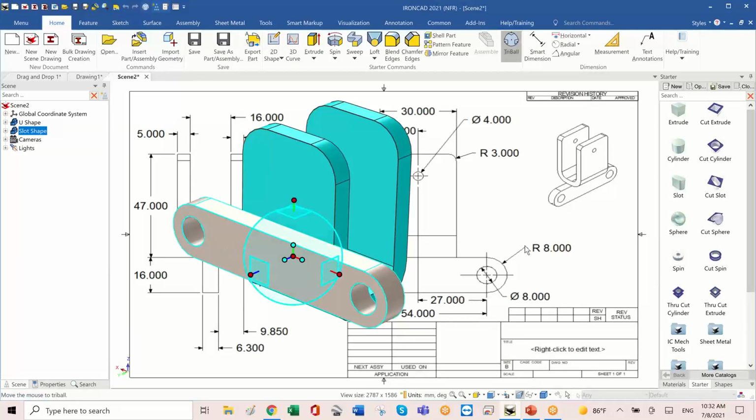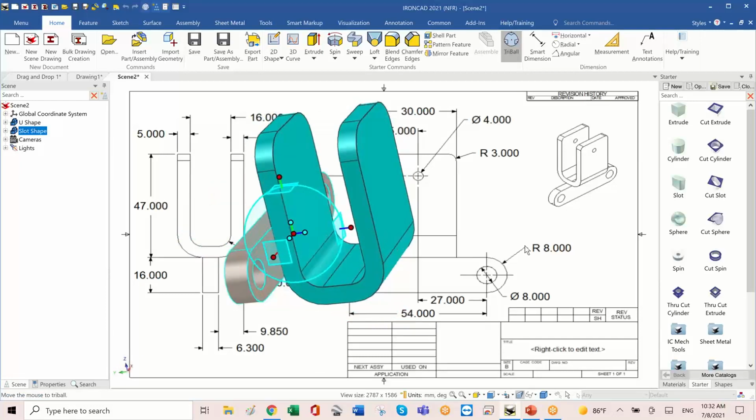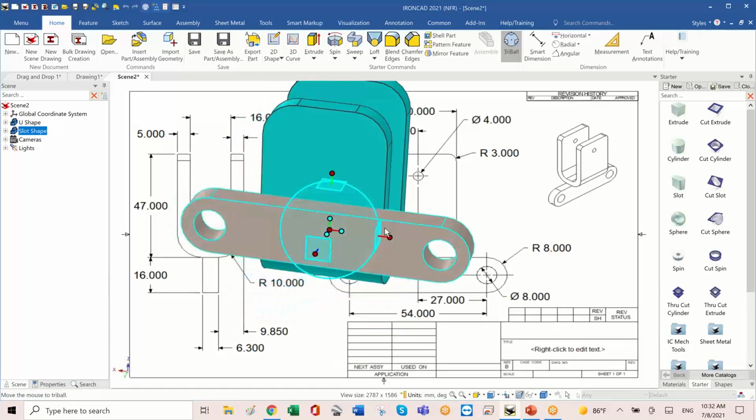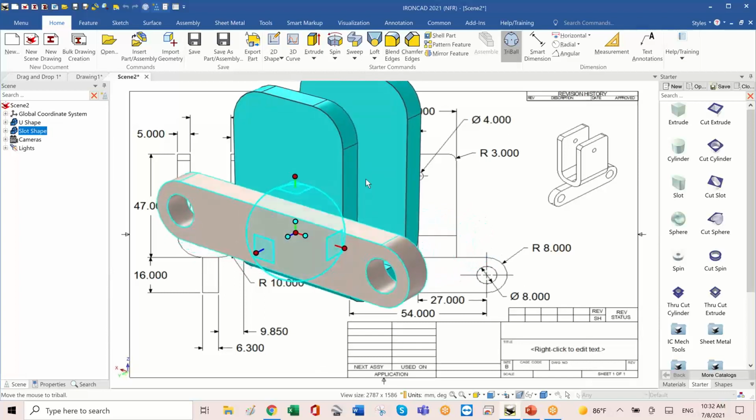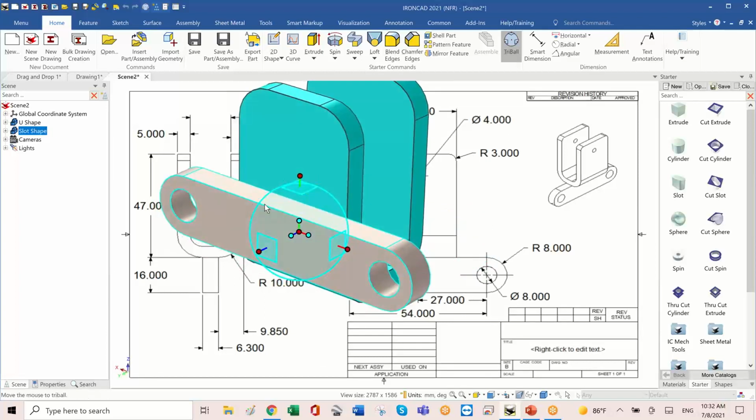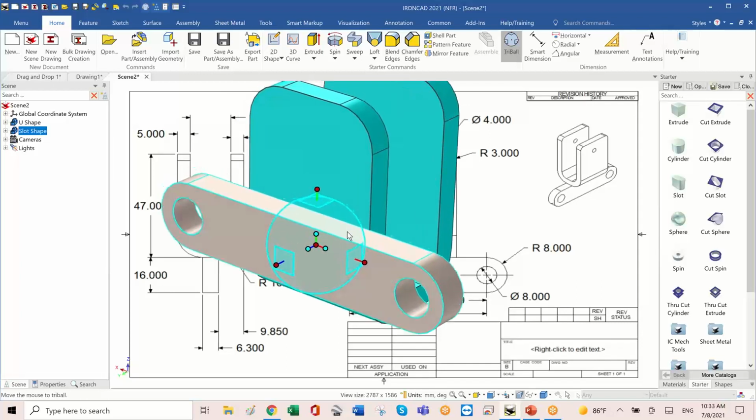The Triball is how we move parts around. So I said this Triball, which is now located at the bottom of the slot, I don't want it there. We have a number of webinars, by the way, on the Triball that are available. But I want to unlock the Triball, so I'm going to hit the space bar.